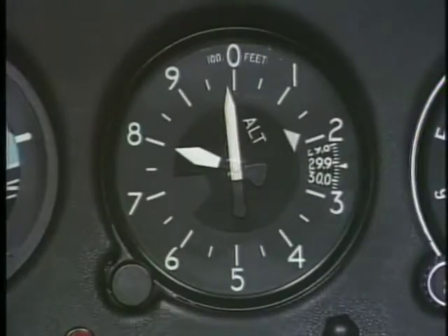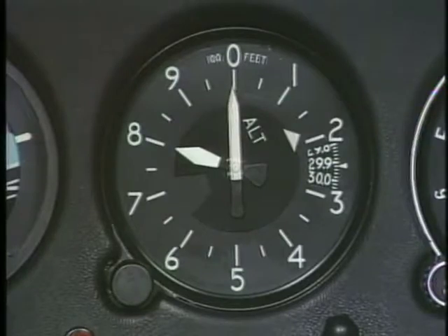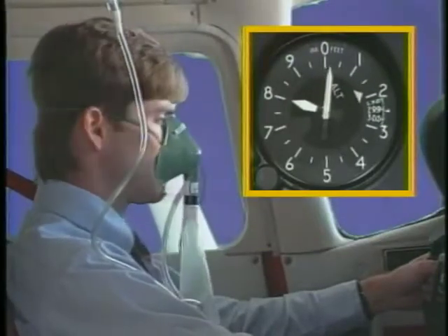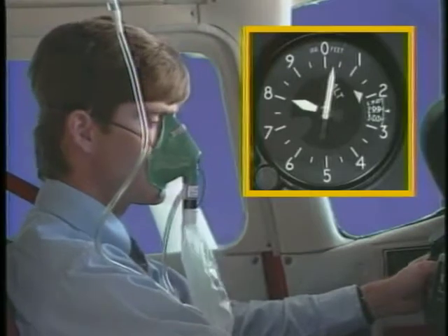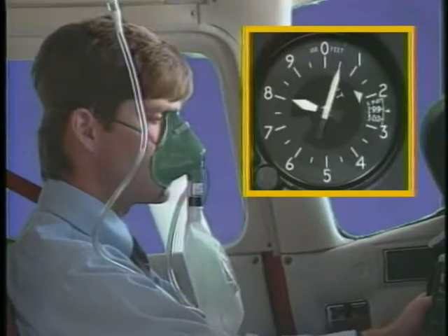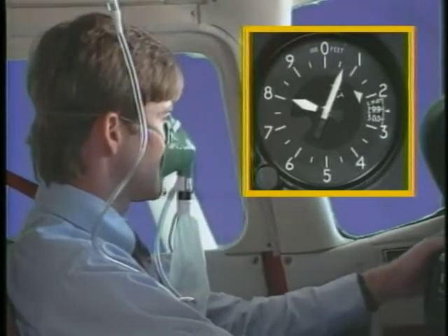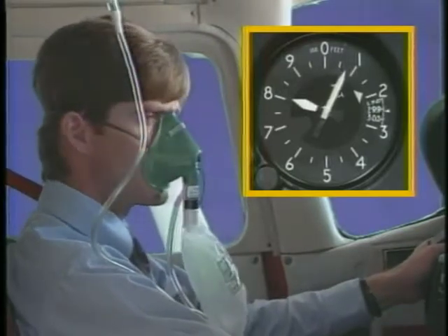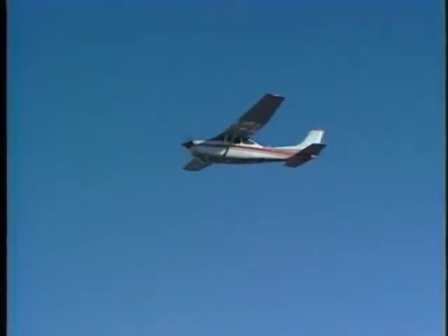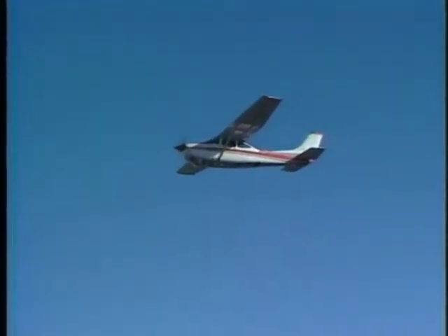As altitude increases, the greater flow of oxygen causes the bag and mask to be pressurized more. This results in less outside air entering the mask. In addition, the higher altitude causes the bag to expand due to the lower surrounding pressure. The continuous flow system is adequate up to 25,000 feet.